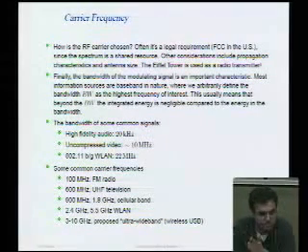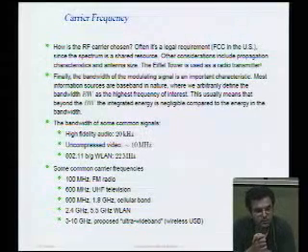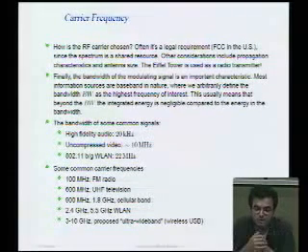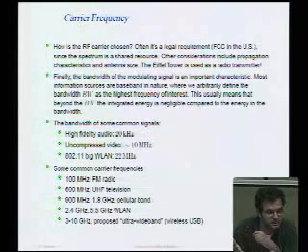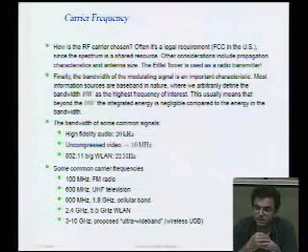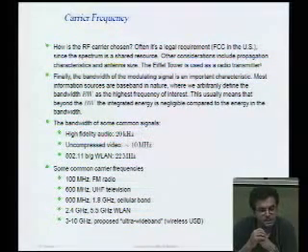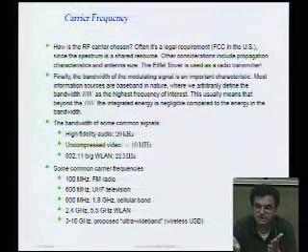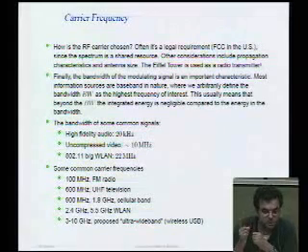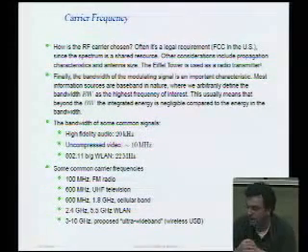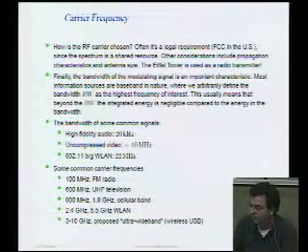So there's basically spectrum allocation that tells you, yes, this spectrum is allocated for, let's say, industrial, scientific, medical uses. There's bands where you're free to transmit as long as your power level is lower than a certain threshold. That's a good example of the wireless LAN band. You guys can transmit as much as you want in the wireless LAN band. No one's going to come and arrest you because that's an ISM band and you're allowed to transmit. But your power has to be lower than a certain threshold. If it's above that, technically you can get arrested, or you'll annoy a lot of people who may beat you up. Either way.